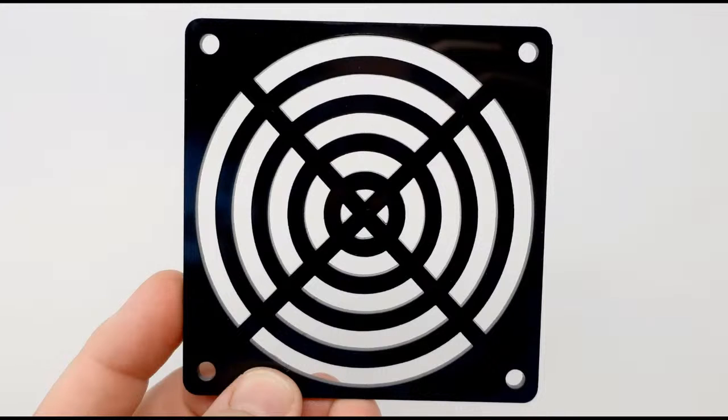without the mess, the extra heat, the laser cutting through multiple pieces, even though it's already been cut, just because there's multiple lines there. So if you're ever sending a file to your laser and you find your laser cutting 3 and 4 and 5 times in one spot, it's because you have 3 or 4 or 5 lines. And those lines may be combined, they may be grouped together, so you don't even know it.